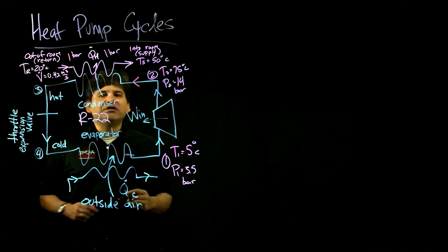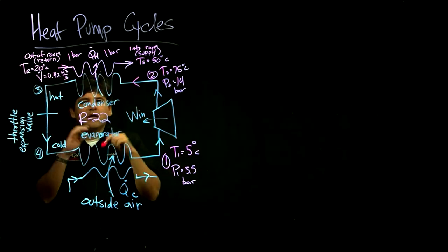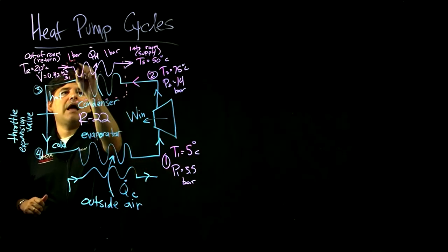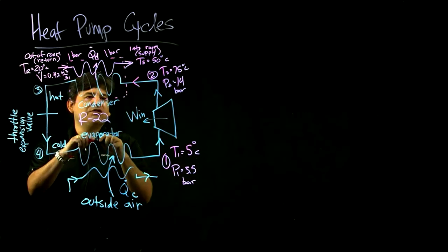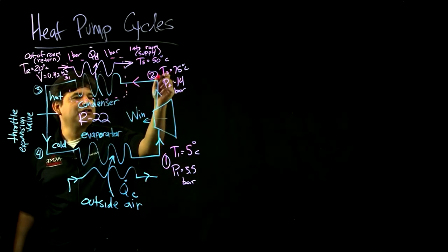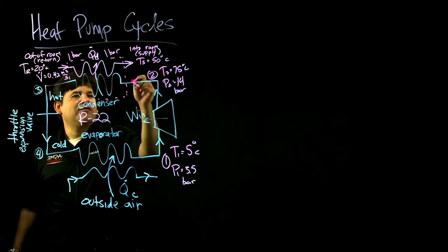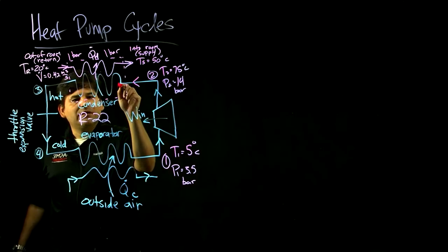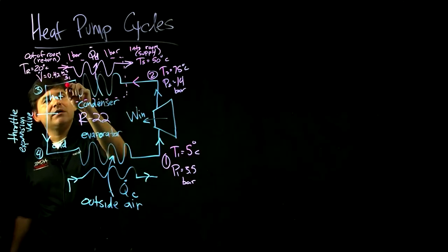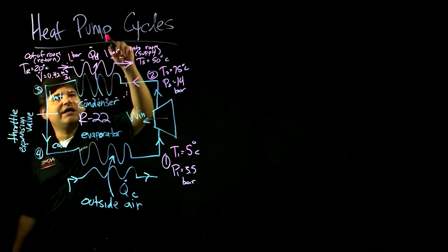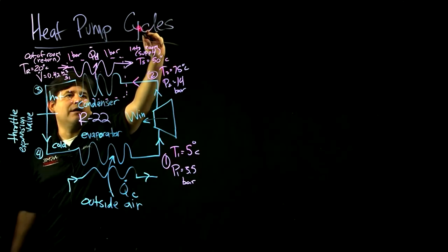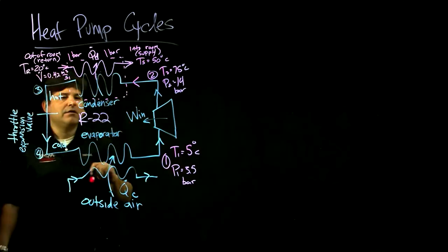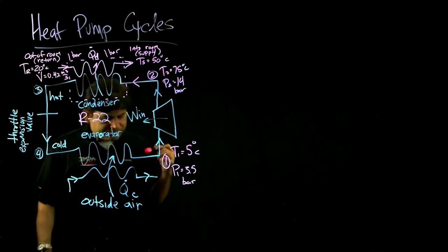So after the compressor, it does the application that we want, which is the condenser. It's called a condenser because this starts off as the refrigerant working fluid at superheated vapor. Then by flowing through this condenser, the vapor refrigerant gets condensed to a liquid. How does it do that? It loses energy at high temperature to the room air. So the room gets hotter, but the working fluid gets colder. And that's what we want. We want to heat the room.